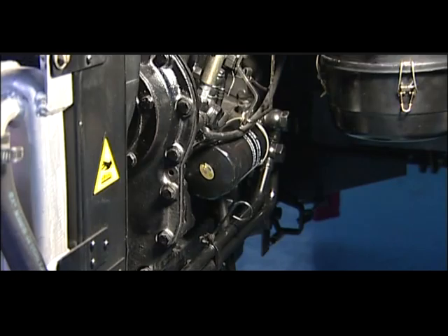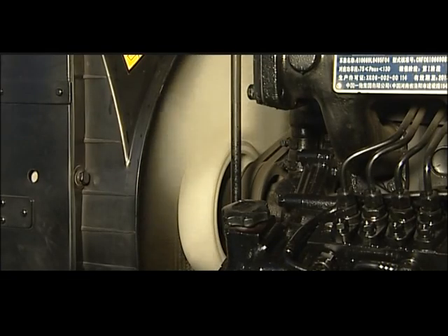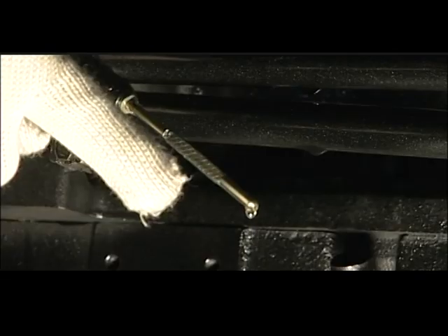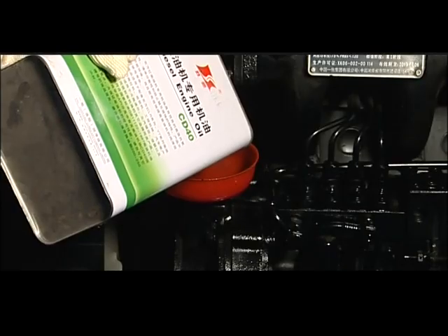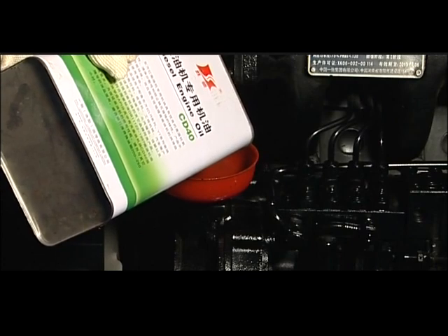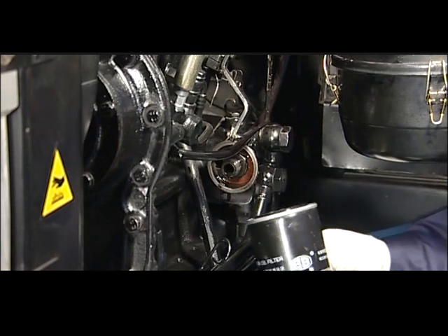In order to prevent the remaining oil affecting the total amount of oil in the filter, when refilling is up to the dipstick scale of the upper-lower limit, shortly start up the engine for 30 seconds. Stop for 5 minutes and test the oil amount. Refill when inadequate. Change the diesel oil filter core. Change the engine oil filter.